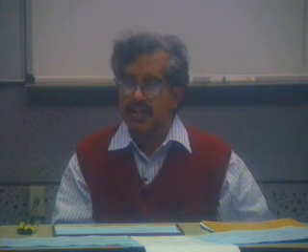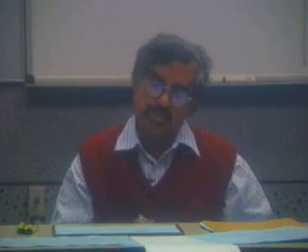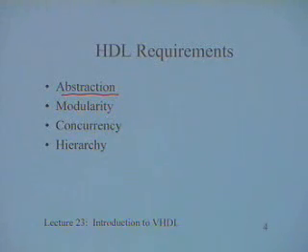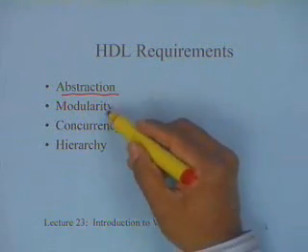They don't need to bother about what the component is going to be, or how many transistors the memory cell will require. They will only look at the overall picture, such as what cache size. They will be doing simulations to find out what cache sizes I should use, how many instructions I should issue simultaneously, and what the depth of the pipeline should be. So they are looking at systems. One should be able to look at that level of abstraction, and then when you refine it, you should be able to go down to a lower level of abstraction. So we will see how VHDL does that.